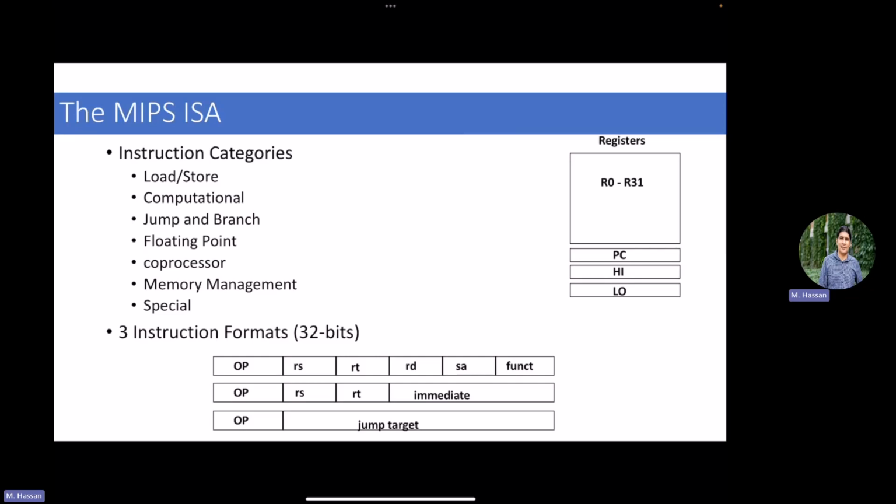So what we said right now is a summary. If I open a manual, I need to look into what the main formats are, right? Usually there are immediate formats, like we talked about, and the arithmetic ones. There are ones that deal with immediate values. If I want, for example, to add 4, as an immediate value, to a register value with the result in another register, then you need an immediate value, right? So these are the immediate instructions. And then there are arithmetic ones and the jump ones.